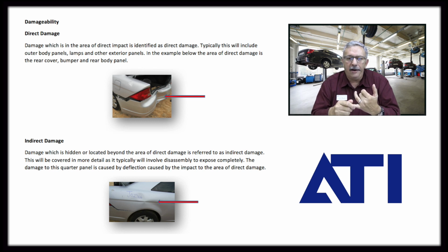That includes things like wire loom fasteners, and in the case of the rear body panel, which we talked about earlier, a lot of those come with a welded-on wire loom holder from the factory that does not come on the replacement part that you would order as a crash part. So we need to keep in mind that the removal and reinstallation of that loom, which requires a spot weld, there's 2 of them, and it requires a spot weld on each one, are not included operations. So the removal part of it and then the reinstallation, we need to add that to the estimate.